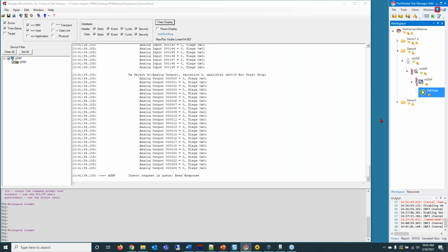Let's say you were unable to find the issue and you had some information from your history of the tests that you've run, and you did want to output the log, as one of the questions asked during the last Q&A session. Just to tag along more information, you would just go over here to File, and then you've got your Save Protocol Analyzer. We've got text and XML. You could then output the tests that you've run, the diagnostic information you have, and potentially take that to a coworker or someone who maybe has more experience with the protocol and see if they can help you figure out what you saw potentially in the field, after you send it back to them in the office or something along those lines.